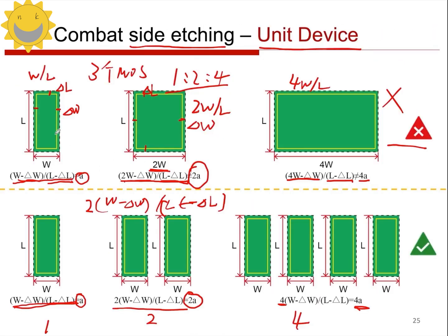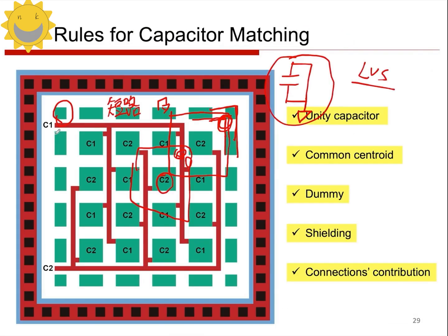It's similar to this, right? You can see that this capacitor has already been separated, right? Now, I can ground these surrounding capacitors, and they won't have any electrical connection with the capacitors inside. So this is the dummy device, right? You can see that here we've actually used two techniques. One is the matching of the supply capacitance, and the other is the dummy issue, right? These are all consistent with what we discussed earlier.